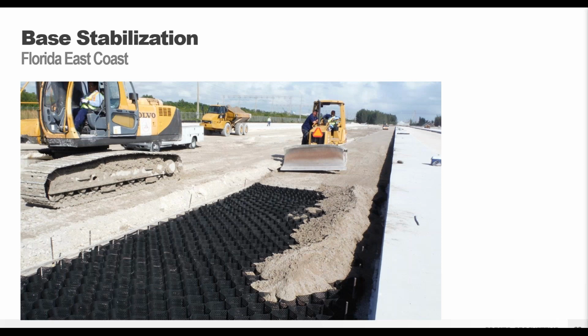Here you can see the sand being filled in with the front end loader pushing that sand into all of the cells. And you can actually see a compacting roller in the back, allowing for that sort of staggered installation process that we've talked about a little bit. It's great to have this sort of staggered subsequent installation to help reduce your construction time.